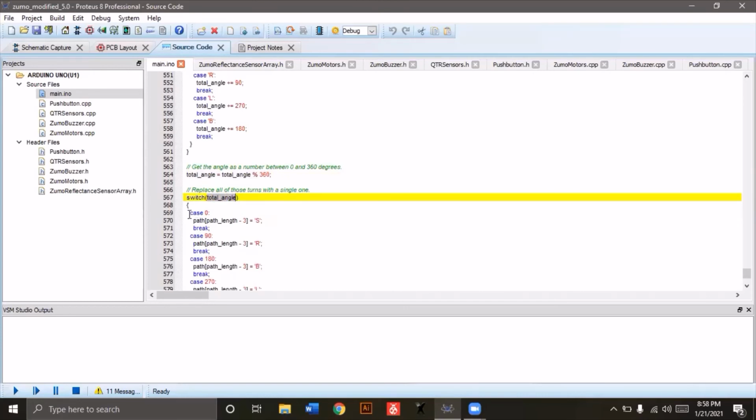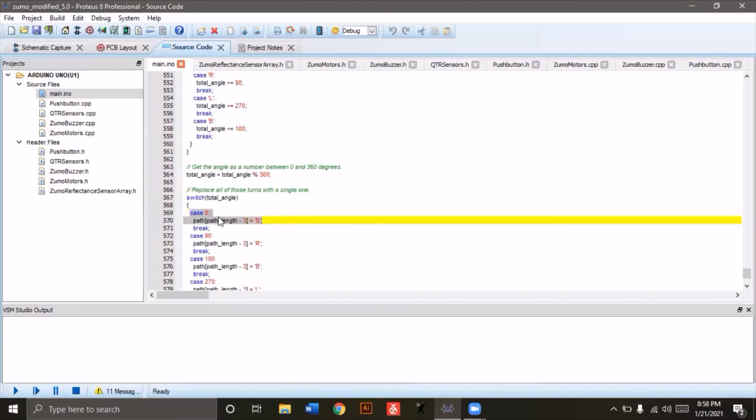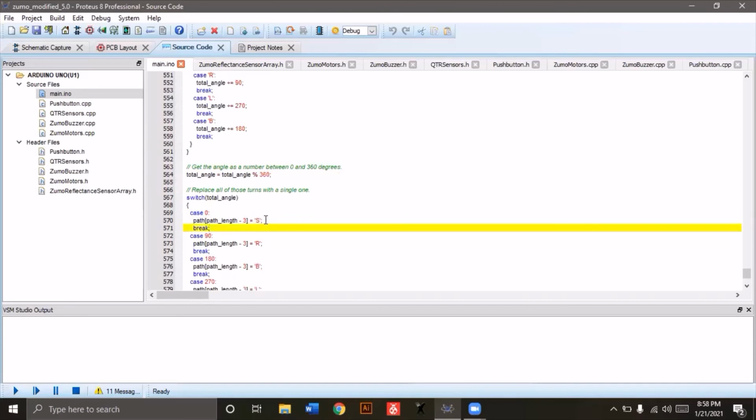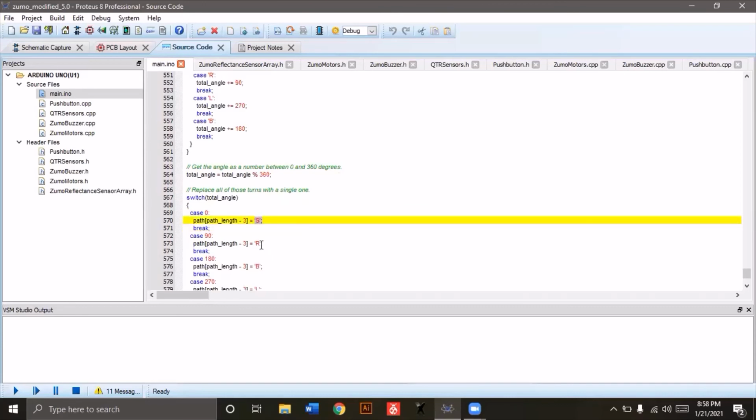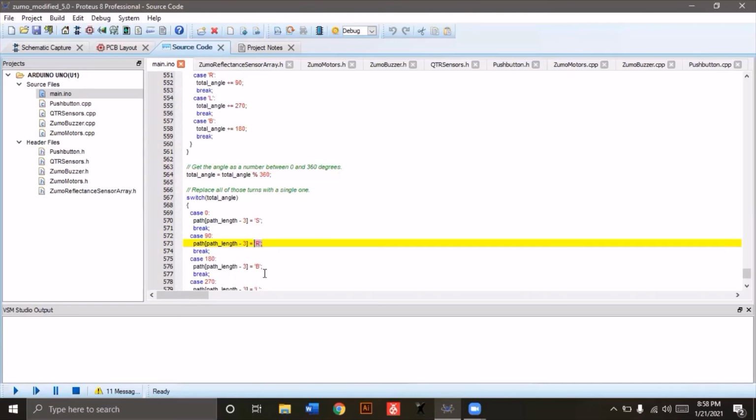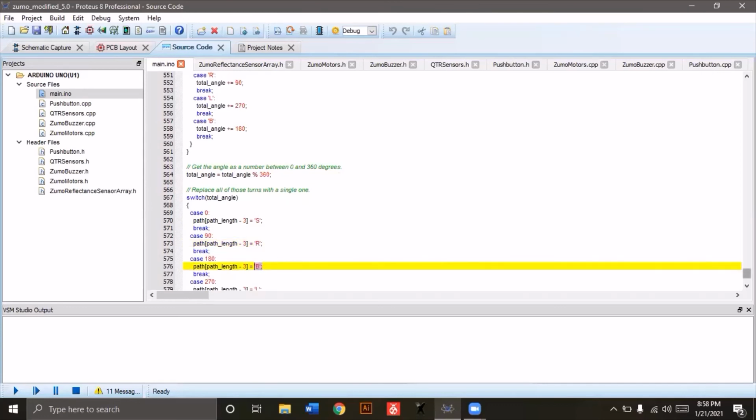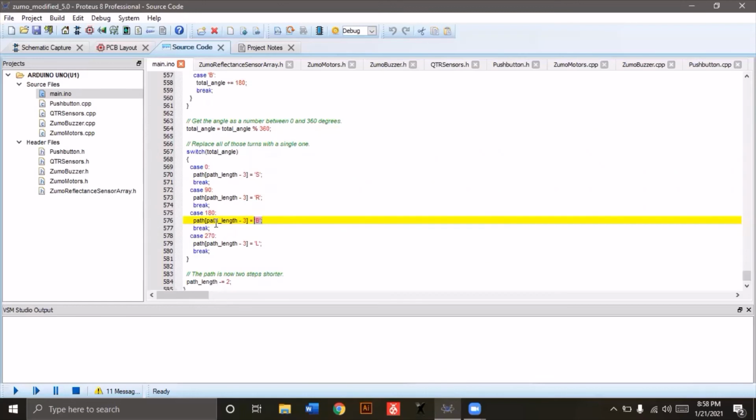And so for these conditions, if the angle is in this criteria, it will just call the function S. If it is 90 degrees, it will call the function for right, because at the B point it rotates 180 degrees whenever there is no sensor in front of it, and at right we make a turn of 90 degrees, and at straight there is no degree turn, and at 270 because whenever we have to turn left, we will turn 270 degrees.